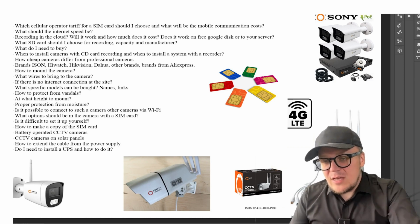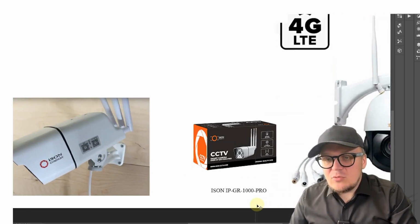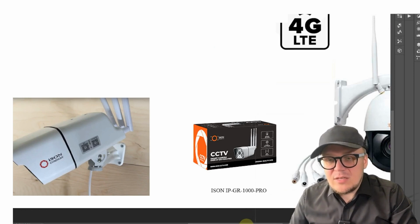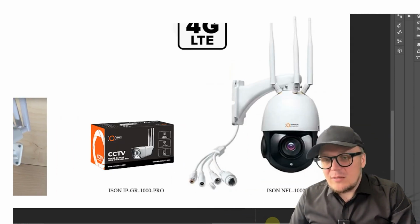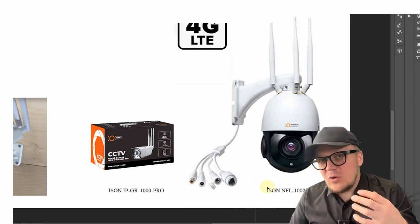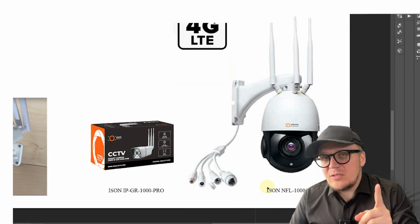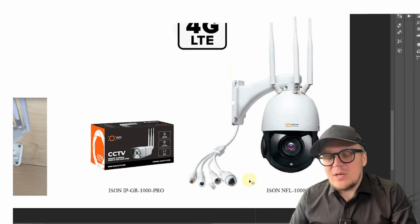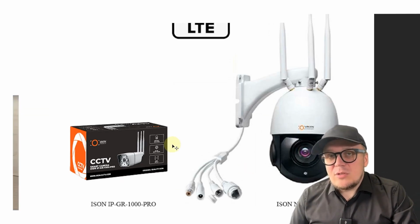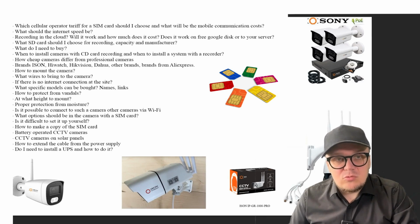If we are talking about the ISON IPGR 1000 Pro camera, it is permissible up to 20 meters to connect to the standard factory power supply. If we are talking about ISON NFL 1000 Pro cameras, it is up to 10 meters. Again, there is always the option to buy a more powerful power supply. Also, do this only in the store where you buy your surveillance cameras, because there are many nuances regarding power supply. And there is always the option to connect through an outdoor power supply. I just demonstrated it to you visually.